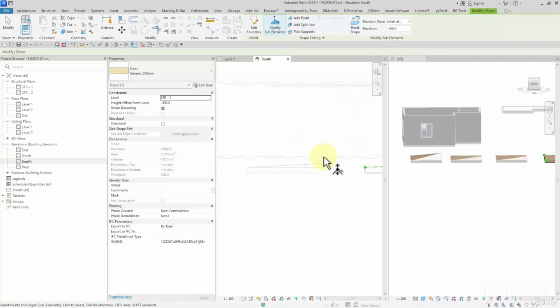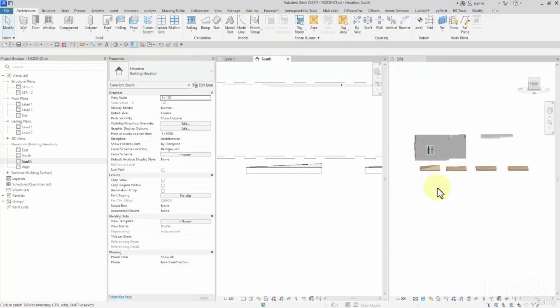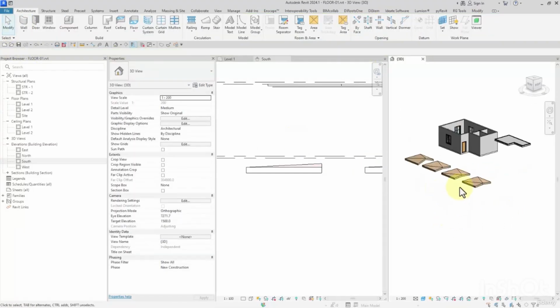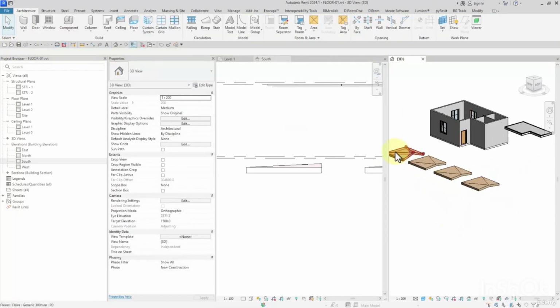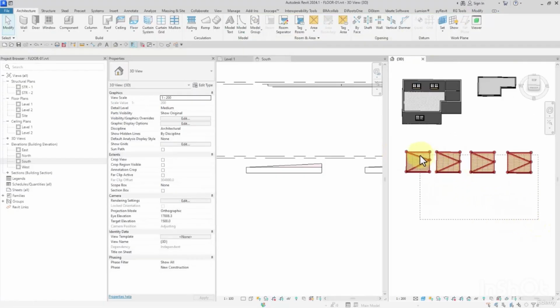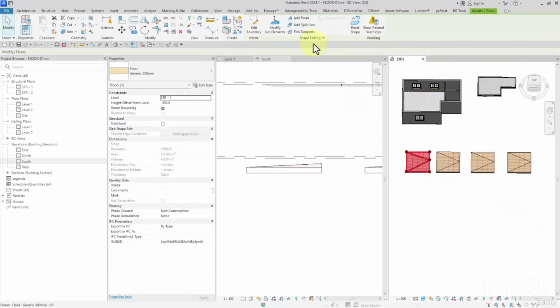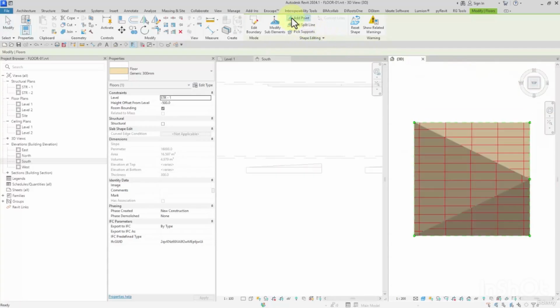Watch this. This has been considered in relation to the internal origin, and you can set or specify whatever options based on your needs. Again, I want to select them, top view at point. So these are the options here. If we set it to along surface, we can specify the offset from surface. But if we set it to absolute, we will only specify the elevation of the element from the elevation base coordinate.